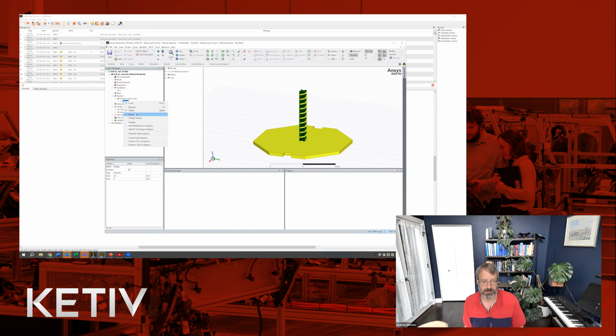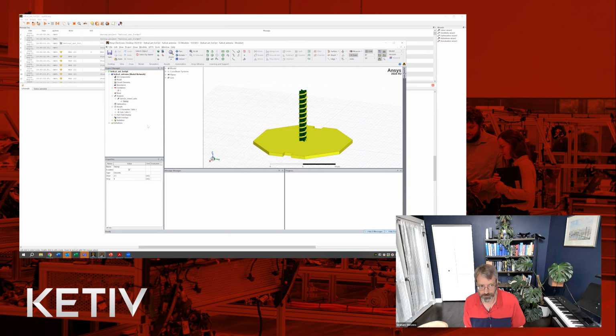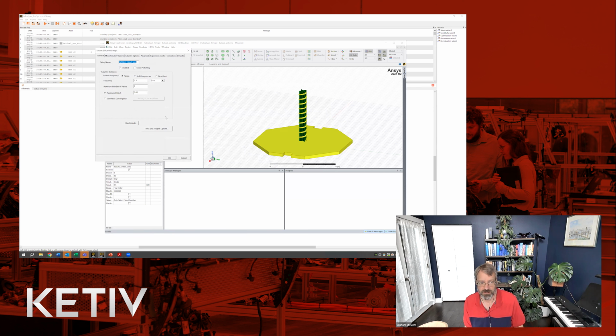So we might have sweeps where we only have 20 points in the sweep rather than the usual 500 or 1,000. Or we might eliminate the sweep altogether and just disable the sweep, depending on what my outputs are. I might change the analysis settings here to first order basis functions, which solve a little tiny bit faster than mixed order.